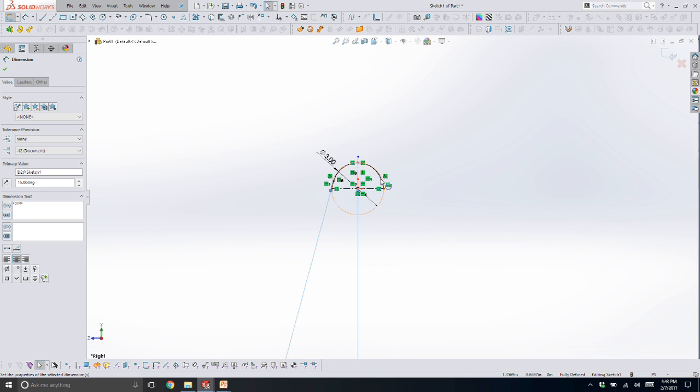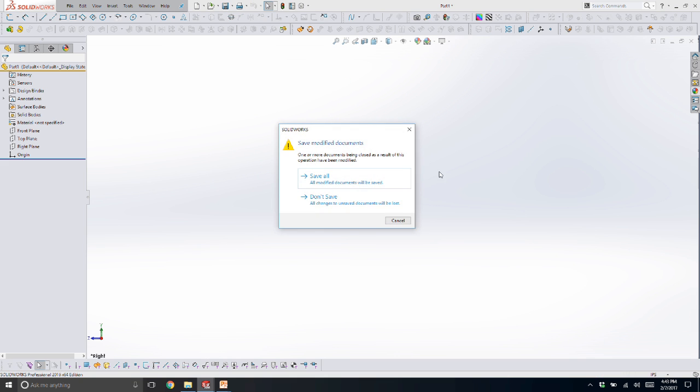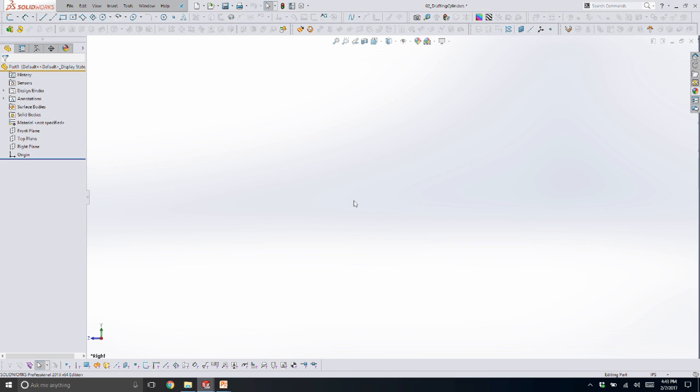One thing that doesn't work: if you need a really ridiculous draft angle, like 15 degrees, you may want to start trying something different, like a spline to approximate a circle, just because of the amount of deviation that you see here. But it's a useful little technique for building in draft to circles.